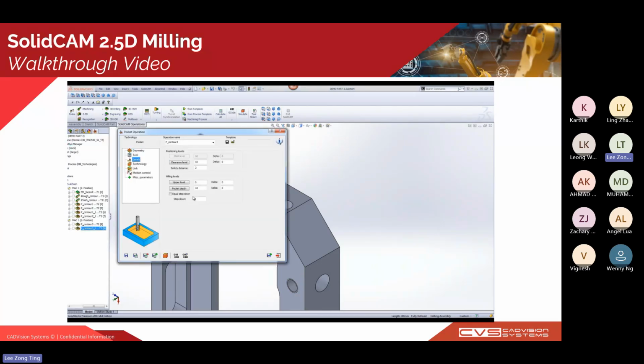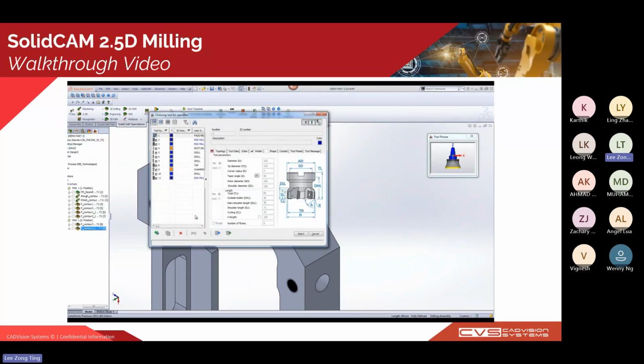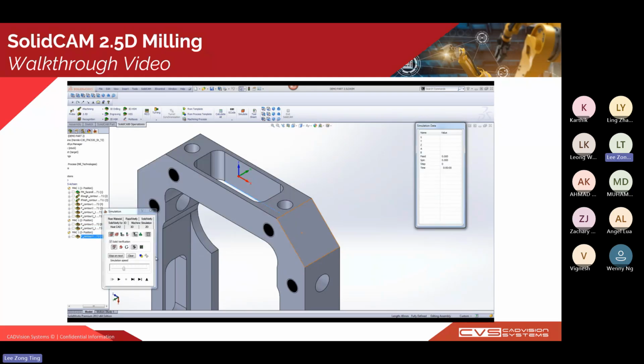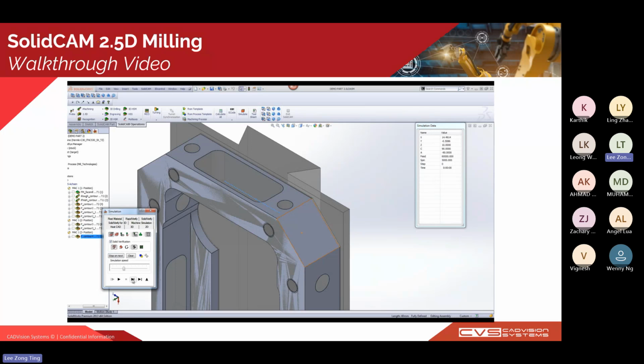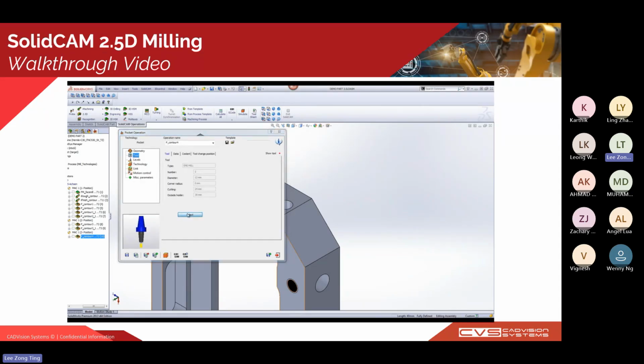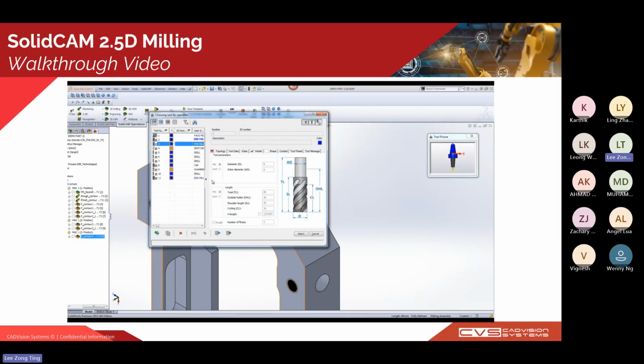So I select my geometry and the tools I'm going to use. You can see here there's a tool table that Tanya mentioned just now. And we'll also specify the level, the technologies, and the ramping strategies. After I save and calculate and simulate it, I found out it is not what I wanted, because we chose a helical ramping strategy and there's not enough space for it to do a helical ramp. So we change it to none, so we don't have any ramping strategy.